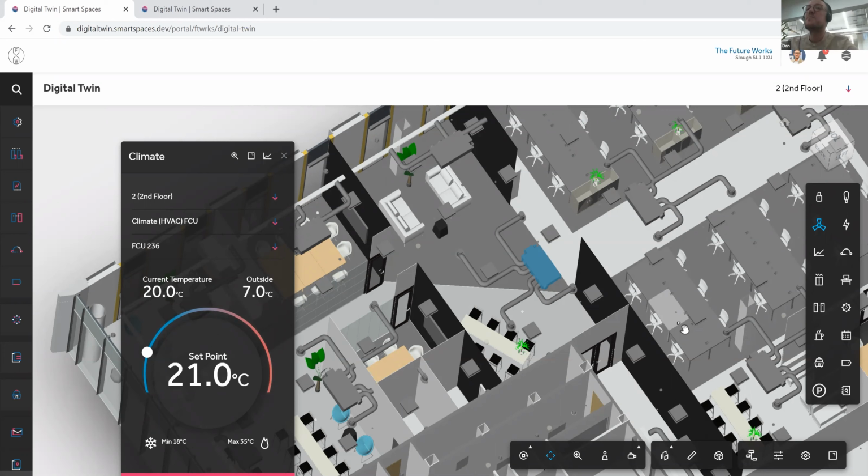Well, we have it already, but it's quite rudimentary. You know, it's more around occupancy. If this floor is not being used, we can disable the AC or turn the lights off. We can also alter the schedule based on booking. So if someone books the space, we'll bring the schedule on in line with that. If the space is not booked over a week, we can switch it off. And so that's our sort of simple rules engine we have deployed at present. What we're looking at now is looking at every single data point and then running an algorithm against that to understand if things are operating outside of the designed operations.